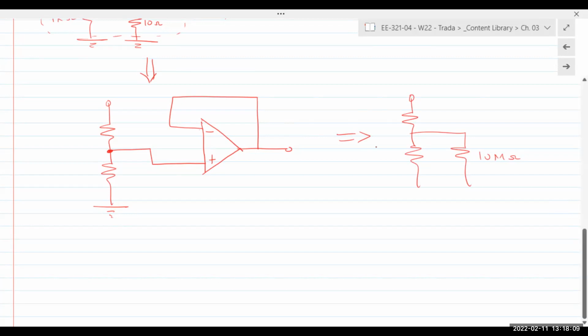But even if you take really the worst one, let's say it has 10 mega ohms and you have 1 kilo ohm here, you apply voltage division, you go through your analysis, and you would still obtain Vx is equal to 5 volts. So 5 volts is going into the op amp here, and you get 5 volts at the output.